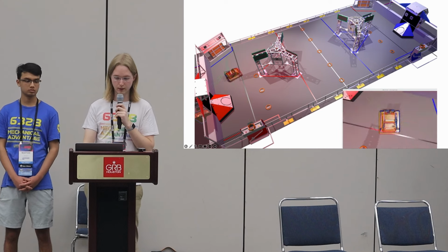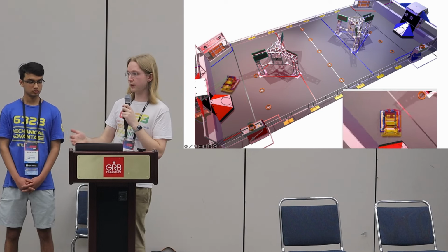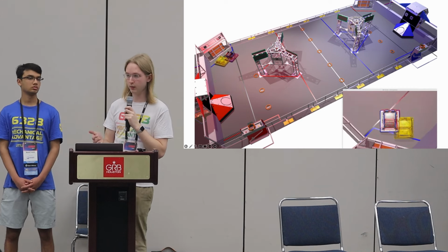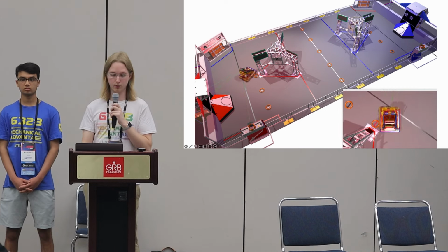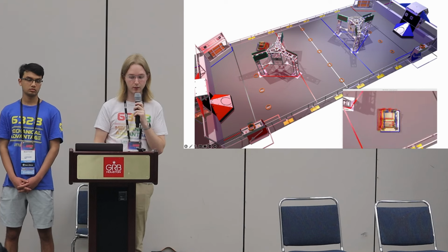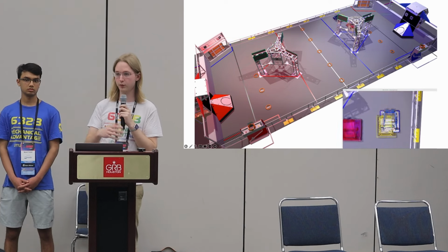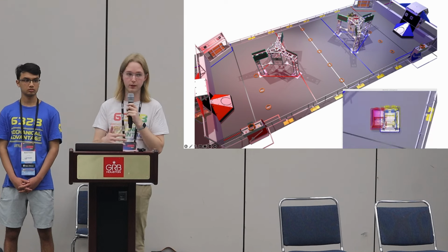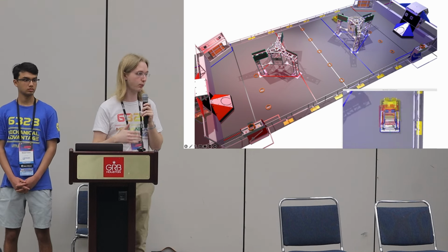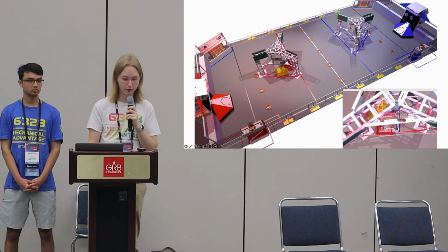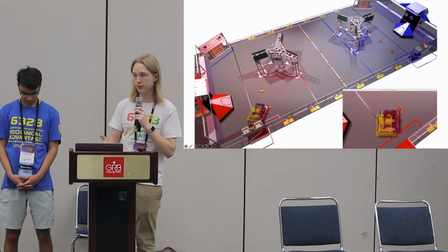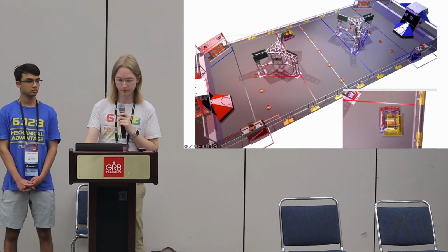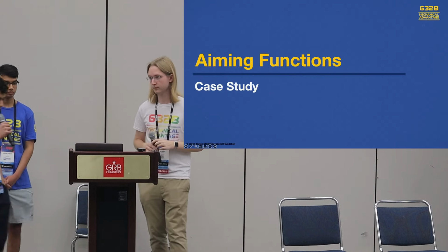However, all of these filtering techniques didn't come out of nothing. We developed this over the past 2 years, relying very heavily on log replay. We were able to tune standard deviations, distance coefficients, extra filtering, all of that, based on real log data and looking at what the robot would have done with different options if we were running all of those possibilities in a match. So AdvantageKit was really absolutely essential to us developing a robust pose estimation system. But we don't have to limit ourselves to vision.